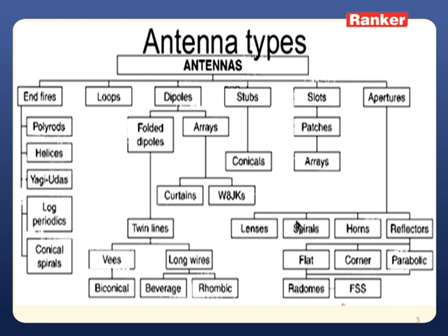A spiral antenna means the structure of the antenna is like a spiral, and it is also called a helical antenna. Helical spirals will be there, or rectangular spirals. And next, horn antennas, which are completely a flared out structure. Horn antennas are made up of four or more conductors. A pyramidal horn will be there, a conical horn, a biconical horn, different horn structures. And next, reflector structures. Nowadays we observe these reflector structures widely. For the reception of TV signals we are using parabolic or hyperbolic reflectors.